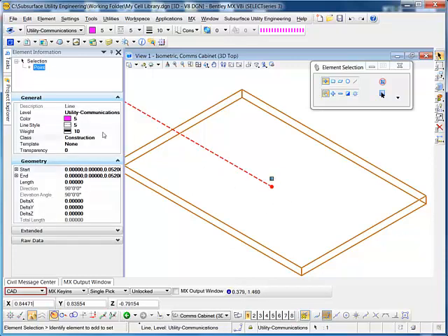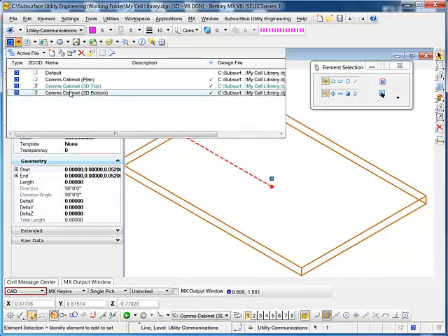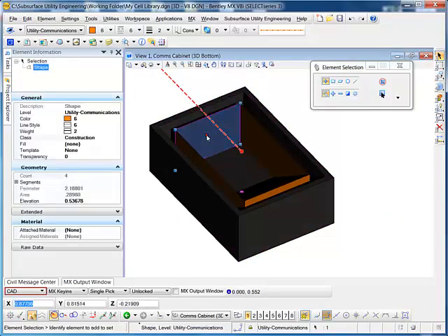We've got the line style 5 construction class point for the top of the cover level of the 3D top cell and for the invert level of the 3D bottom cell, and then we've got the line style 6 construction class elements for the connection regions. So that's all the cells I need created.